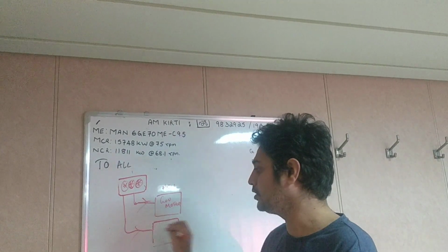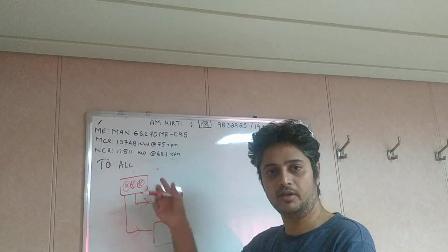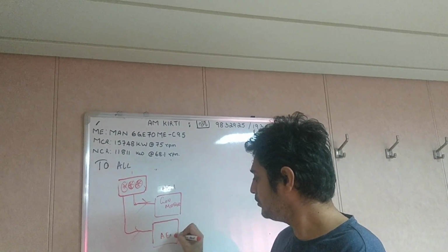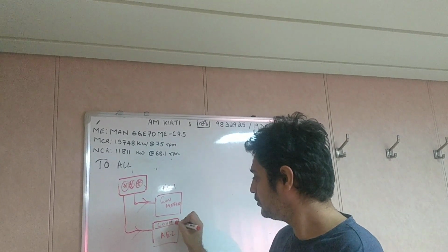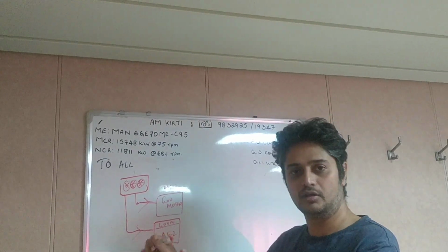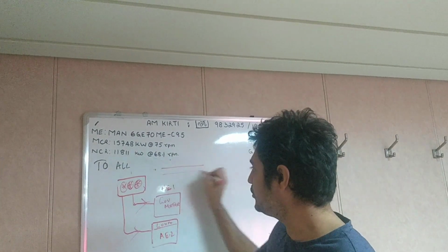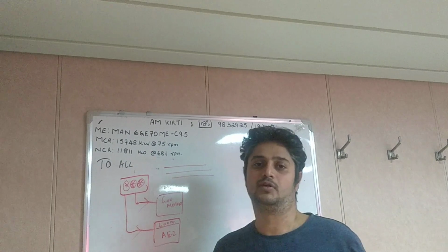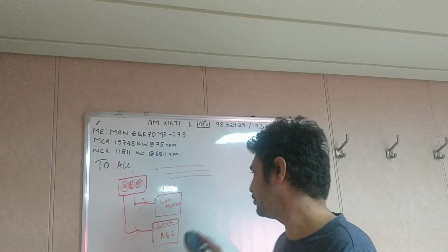These are all voltage signals, analog signals going from the MSB to the governor motor of AE1. Consider this AE2, this is a governor motor. So this will tell this one to increase and this one to decrease a little, so that the bus bar frequency and bus bar voltage are steady, as per the governor settings or droop settings also.